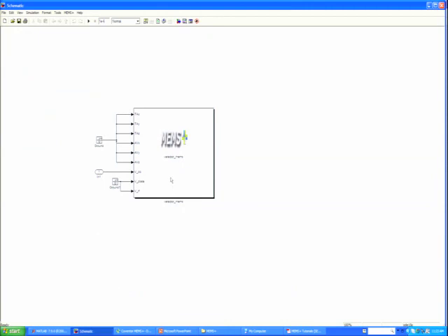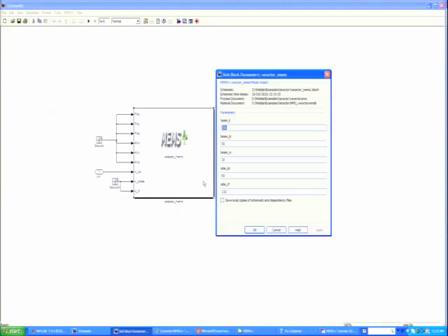If you double-click the MEMS Plus model, it opens up the parameter window. If you remember, I exposed certain variables, the beam variables and the side variables. These variables are now available in MATLAB as something I can change. So at this point, I do not need to go back into MEMS Plus and say beam, you change. I can change that within here, and I can get a parametric simulation done through MATLAB. That's the power of having done things this way.